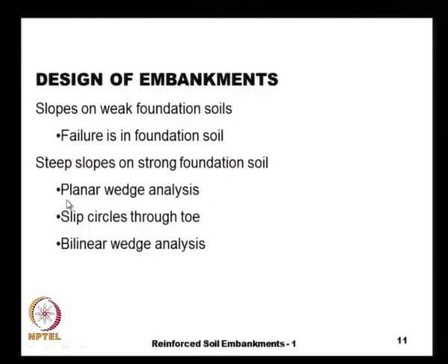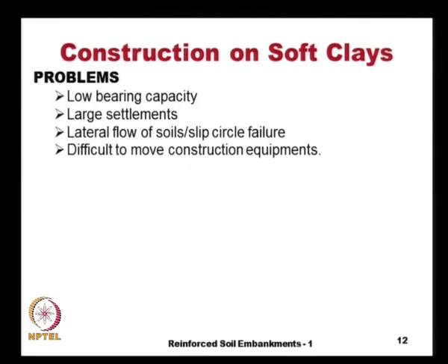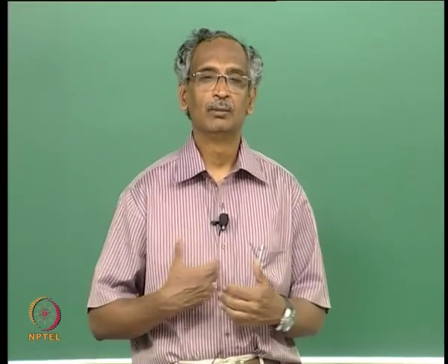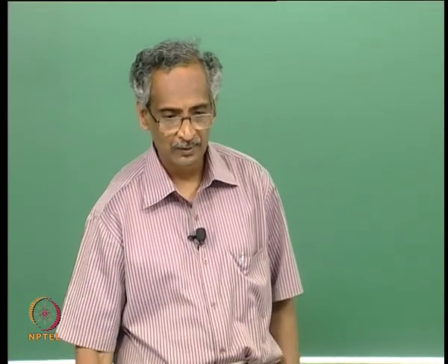And there are different methods for analyzing the steep slopes: planar wedge analysis, the slip circle passing through the toe, or the bilinear wedge analysis. We will see all these methods a bit later. Let us first look at how to construct the embankments on soft soils or soft clays. Usually most of the problems are because of the construction on soft clays.